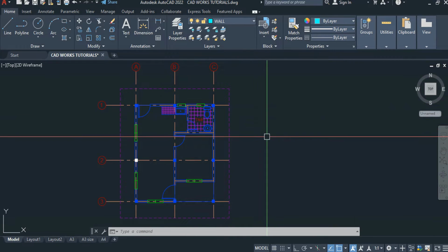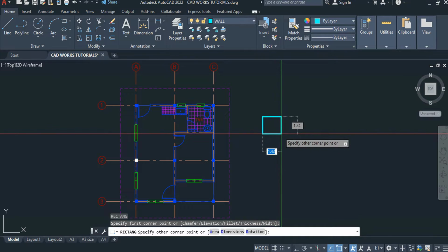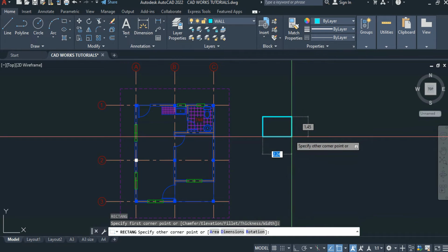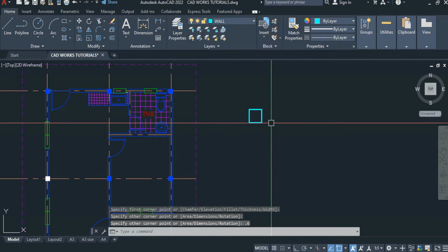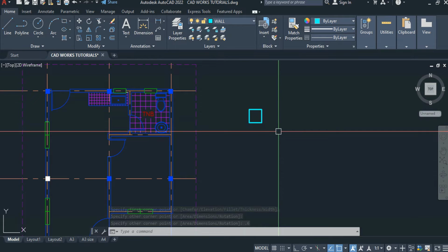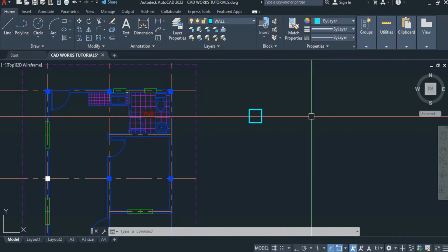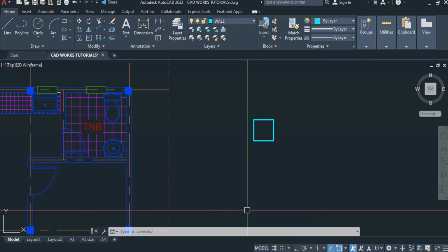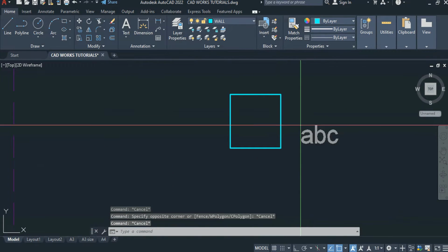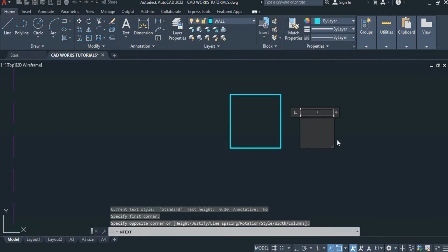So, ang gagawin ko lang dito is I'm going to type REC here, since nasa wall pa naman siya ang aking layer. Just give it a 0.6, tab, 0.6. Now commonly sa mga catch basin, it ranges from 0.5 to 0.6. So 0.6 ang pinakamataas niya, simply because one of the laborers that I asked said hindi na nila kailangan ihati pa ang hollow blocks. Dalawang hollow blocks na lang kailangan nilang ilagay right away for their catch basin. So, if you want to have it on wall, pwede naman siya. Here, I'm going to type text and then place the name CB.